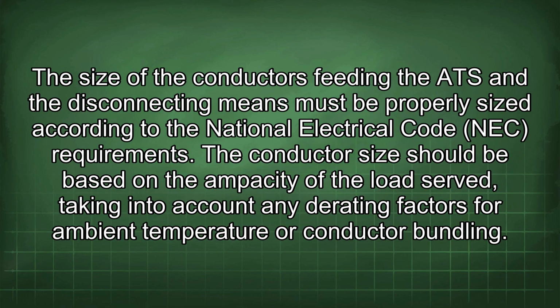The size of the conductors feeding the ATS and the disconnecting means must be properly sized according to the National Electrical Code (NEC) requirements. The conductor size should be based on the ampacity of the load served, taking into account any derating factors for ambient temperature or conductor bundling.